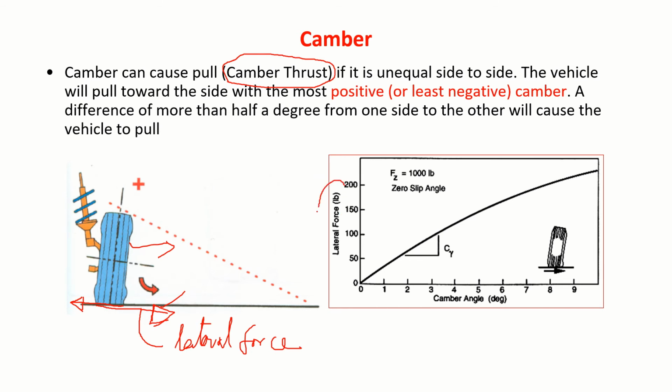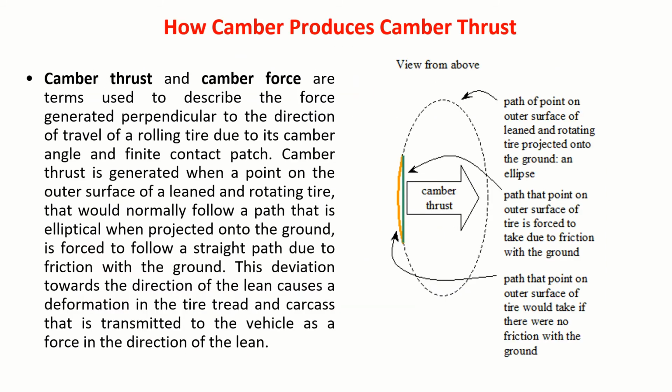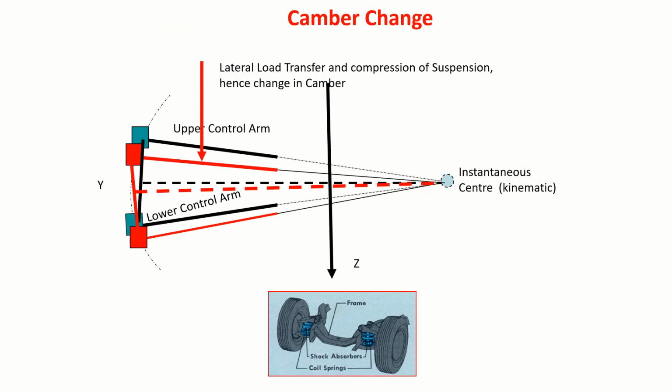Here, this lateral force or camber thrust versus camber angle has been drawn. For a given camber angle, you can read off the thrust or lateral force it can produce. This is how exactly a camber thrust is created.